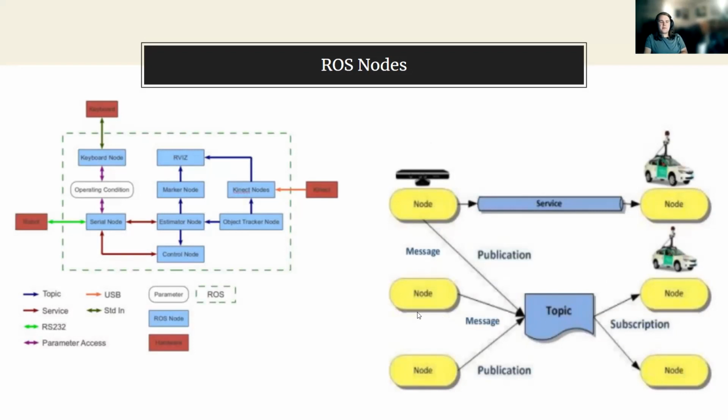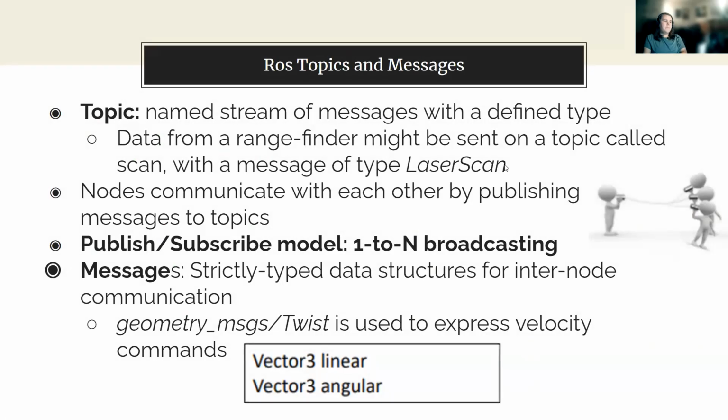So if we get from our path planner saying, okay, move at 5 meters per second in this direction and an angular velocity of this direction, maybe it'll go to this node on the right, and that node will start telling the motors exactly how to move, so we actually get that velocity out of the robot. Does that make sense to everyone, that concept?